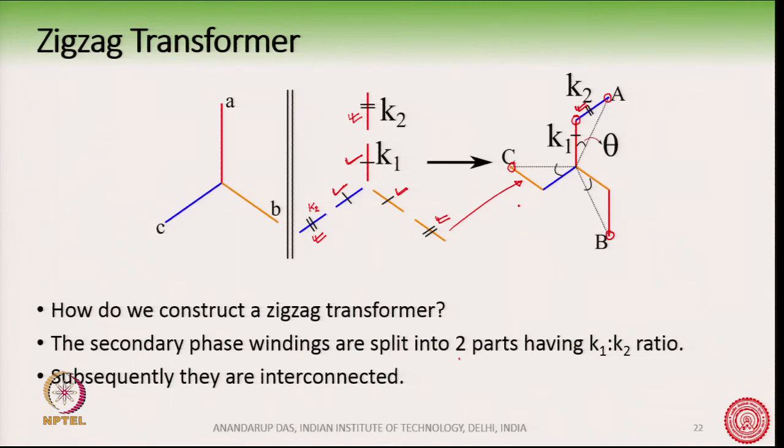There is a particular phase shift between the input side voltage and the output voltage. For example, this is O point and this is also O point, O small a and O capital A here. Suppose in the primary side we have O small a, this is the primary voltage, and O capital A, this is the secondary voltage. Okay. Once we have already interconnected.